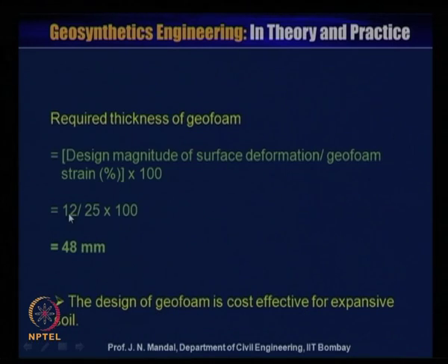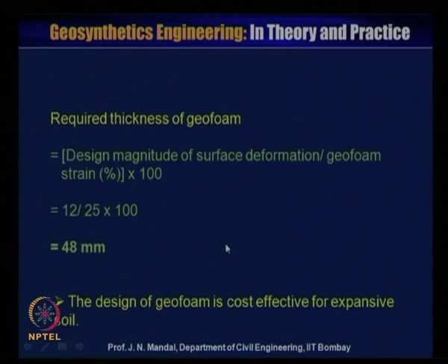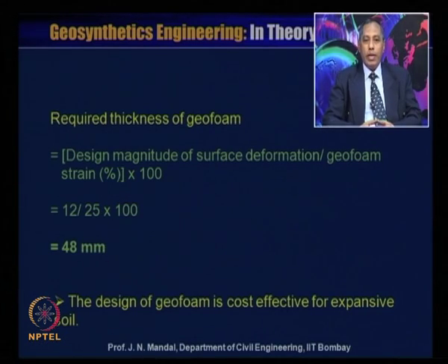And you calculated that for this 40 kilopascal, the compressive strain is 25%. So 12 divided by 25 into 100 is equal to 48 millimeter. So this design of geofoam is cost effective for expansive soil.